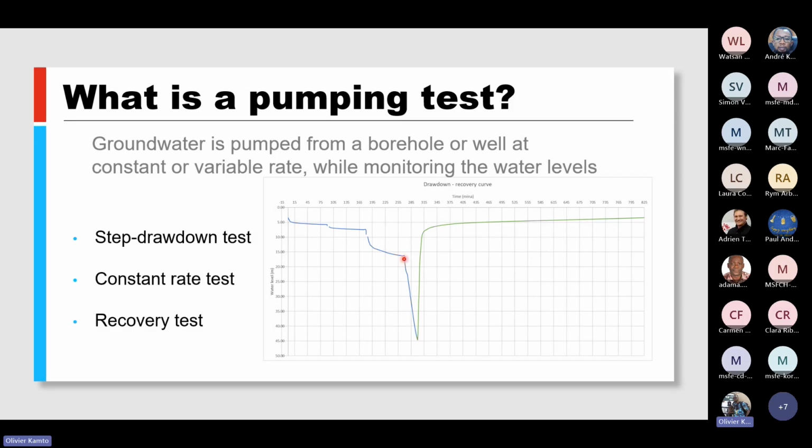I have situations like this one, for example, where there is an issue with this particular flow rate, and generally it's not recommended to restart. So when you're running your step drawdown pumping test, you should generally ensure that the curve more or less follows this aspect.